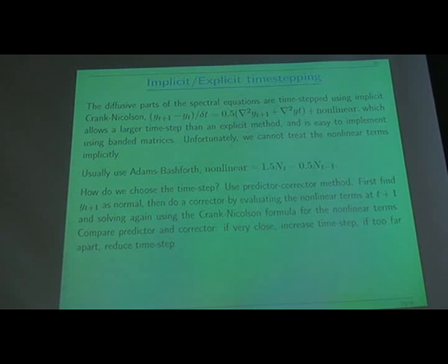So I definitely recommend somebody to use that rather than directly trying to solve a fourth order problem with the fourth order matrix, which is what we used to do. Currently we're using Crank-Nicholson, implicit Crank-Nicholson for the time stepping part of it, which is a common choice. It's a half of the thing evaluated there, so that's implicit because this appears on the right-hand side. But this causes no difficulty because the del squared operator is very, very simple in spectral formulation.